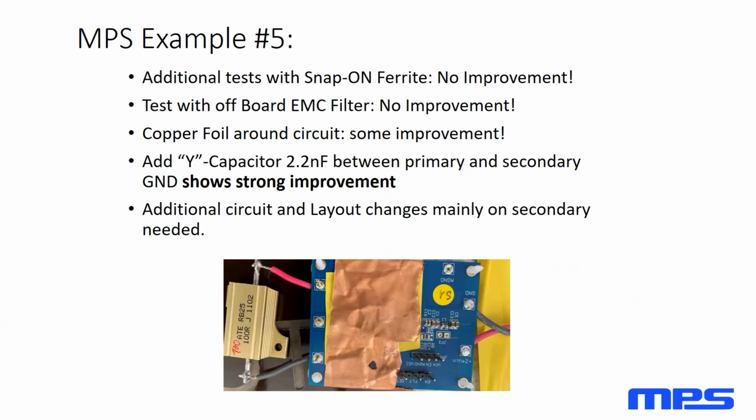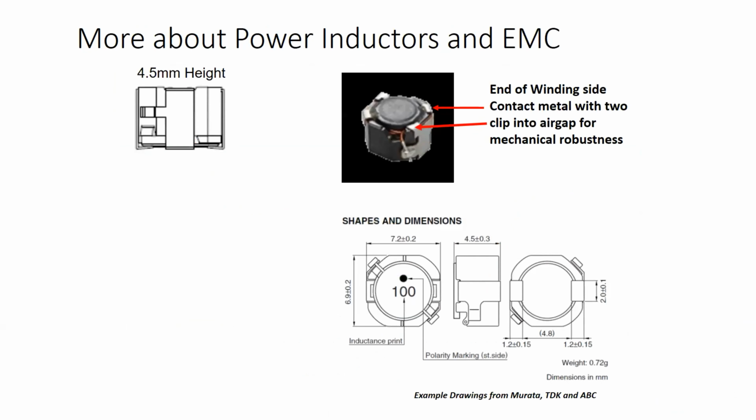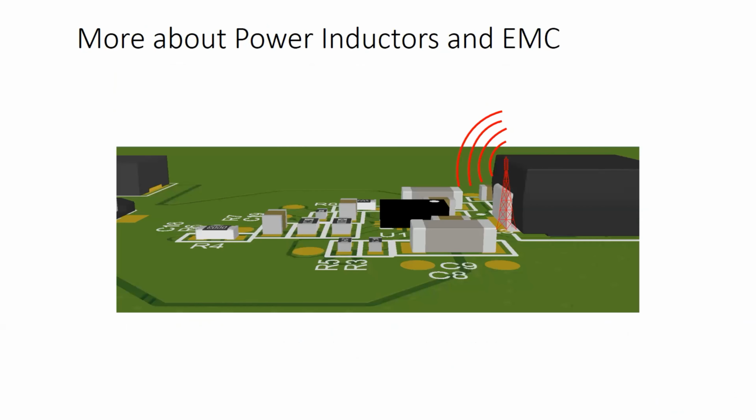And there's another request for an example: high dV/dt area should be small and low profile. Can you show another example, specifically what is meant by low profile? Not sure that's something we have in this presentation, kind of, sort of. I'll have more on that tomorrow. In this example, there is no terminal here. There are inductors that have the mounting only on the bottom, so this metal tab isn't here. This particular inductor is relatively high, right? It's that tall antenna compared to these guys.